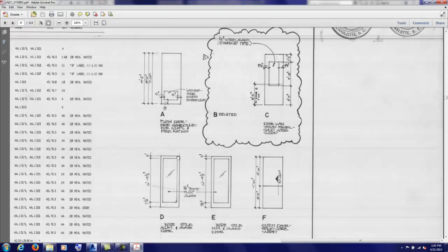And then we'll do this other one that's going to be more what's called a stile and rail door. Stiles are the verticals and rails are the horizontals. We can make that another panel type as well. So in this one we're going to have basically a void and then another extrusion that's going to be the glass within it.